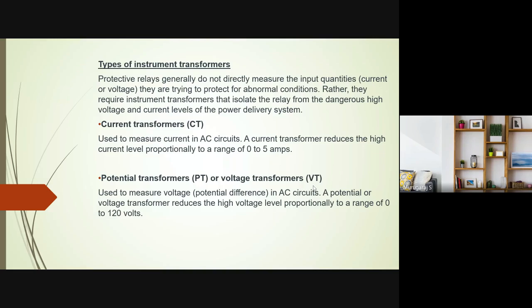So the principle of current flow is that whenever there is a high potential here and a lower potential there, the current will flow from high potential to low potential. And when there is a back EMF in the primary side but no back EMF in the secondary side, it tends to draw more current from the primary side. So that's the reason the motor is drawing more starting current when starting.